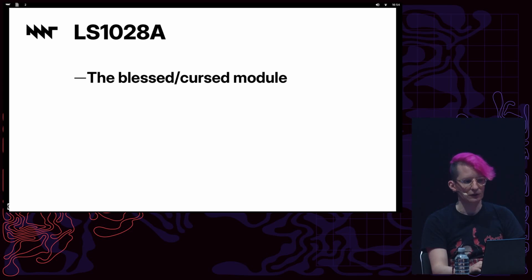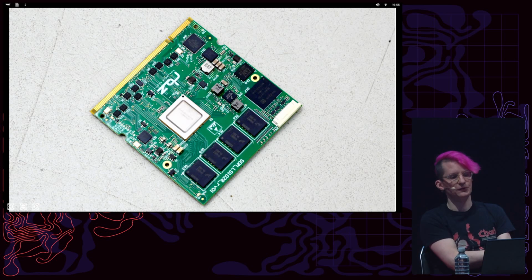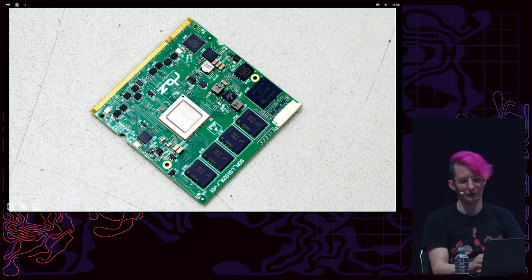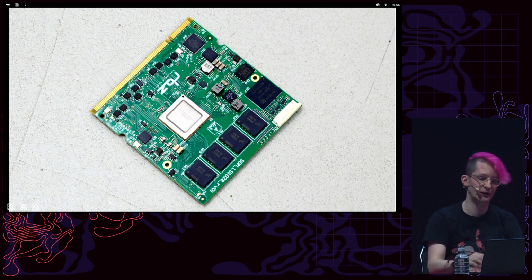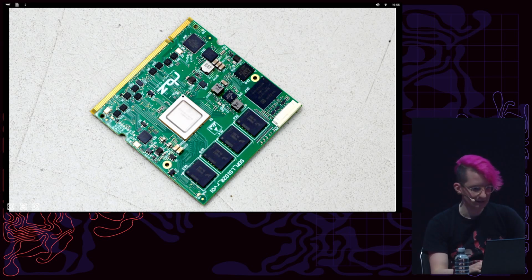There was, though, one Cortex-A72-based processor with graphics integrated that did not need a binary blob to train the memory, which was the NXP Layerscape LS1028A. So you can boot Linux on this processor without any proprietary bits. But to get display output, it needs some binary firmware in the DisplayPort controller. I had the idea that for purists, we could work around this with some PCI Express-based add-on, but I didn't get around to that.